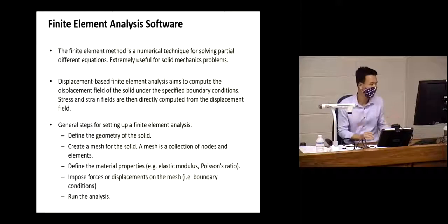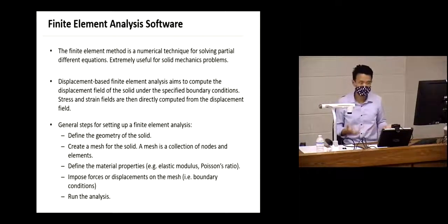Now, what you need to give then is the material properties, because that is what you want to analyze. You can be using steel or other materials, so you have to define that. You have to tell the program what you're using, because it's going to give you only garbage if you give it garbage. So you define something so that it can calculate for you.